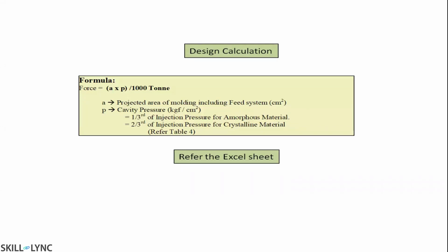Once we get that calculation, we get the mold base for the different tonnage machines. It starts from 5 tons, for very toy-like components. We can mold them in 5 tons; usually they call it baby tons, 5 to 10 tons. There will be very small parts like nylon gears inside watches. You can see the small gears, right? These are all molded in less than 10 tons only.